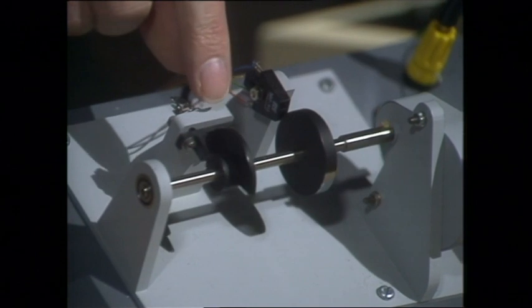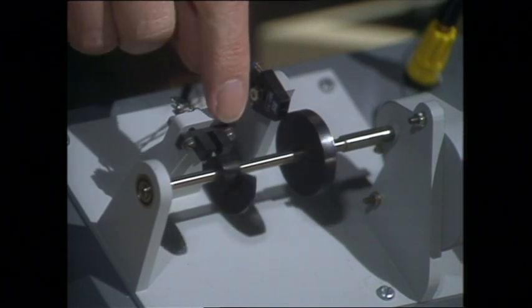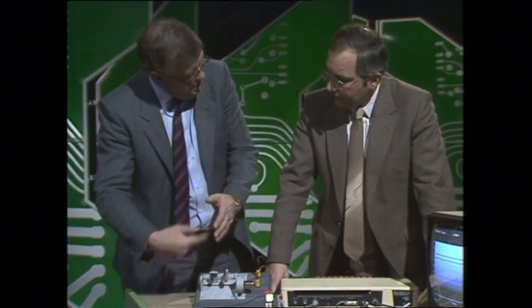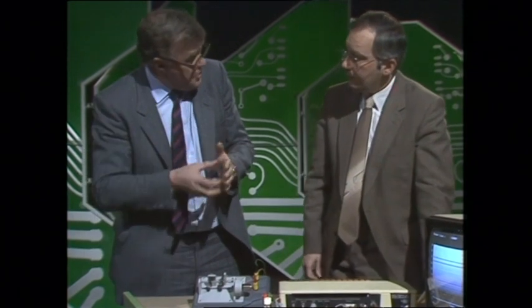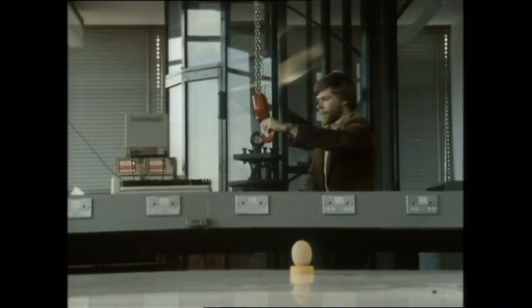Again, here, we've actually got a disc cut in half, which is cutting a light beam, completely cutting the infrared beam between there and there. Of course, very often this disc is actually a complete disc with holes in it, so it can not only detect the speed, but it can actually detect the position of the shaft. Yes, that's right, Mac, and recently I saw a hoist at Southampton University which used that technique.